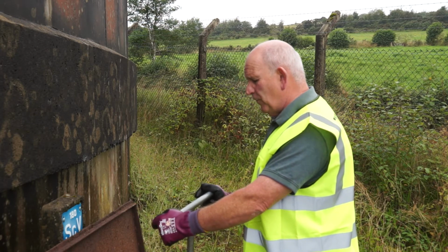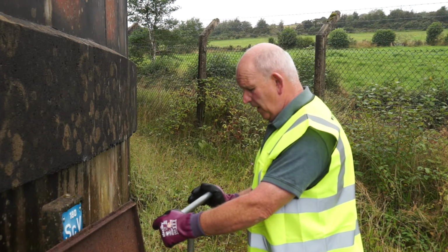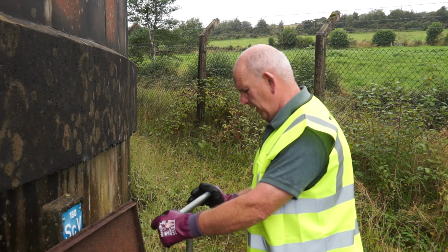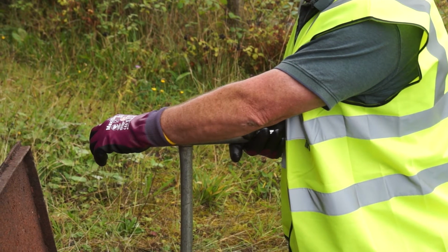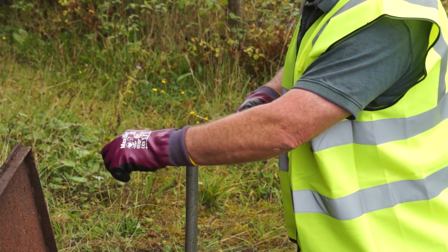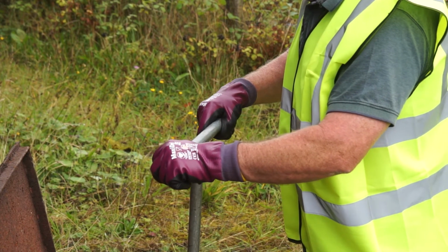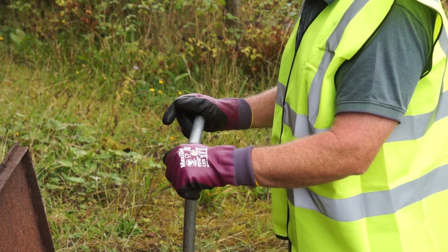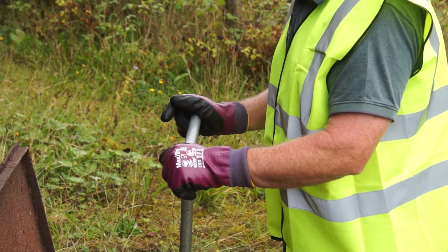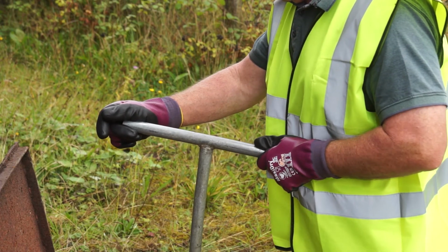So now I'm going to reverse the process and slowly close the valve in the opposite procedure that I opened it. It is vital to close any valve in the distribution network slowly. Water is incompressible, so if a valve is closed quickly, the water has nowhere to go, and the energy of flow or pressure ricochets through the distribution system, causing structural damage and frequently failure, resulting in burst mains.